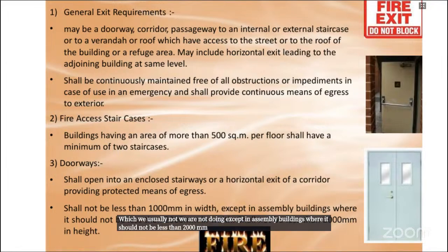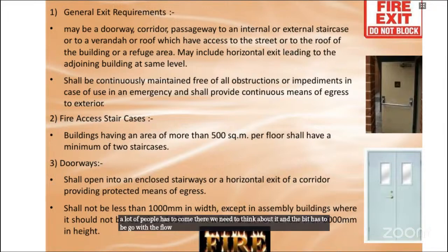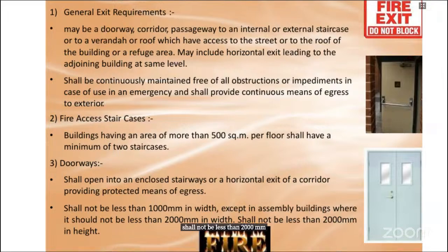So when we are doing halls or some assembly areas, where a lot of people have to come into the doorway, we need to think about it, and the width has to go with the flow. Height shall not be less than 2000 mm, right?